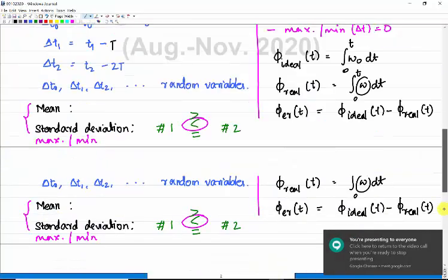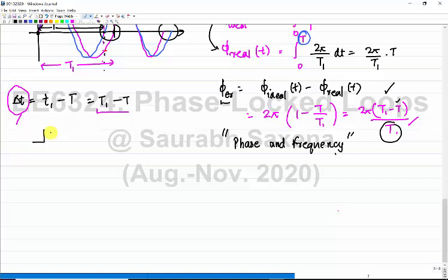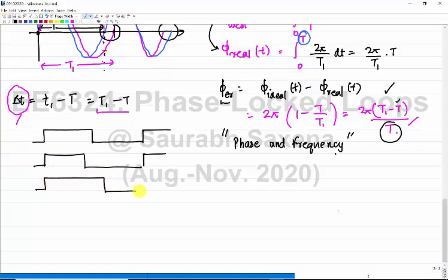So what happens is that in some kinds of clock signals, let me just draw a square wave. Whether it's a sine wave or a square wave, I can just draw this clock period. I may have this, another, maybe I have this. When you are generating a high frequency clock, you can have all such kinds of options. Here, all the rising edges are aligned, but falling edges are not aligned, and this is normally called duty cycle error.